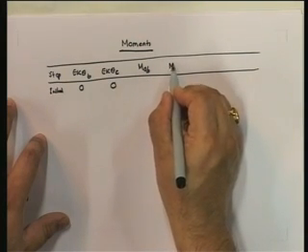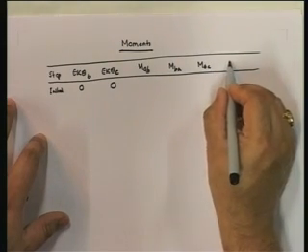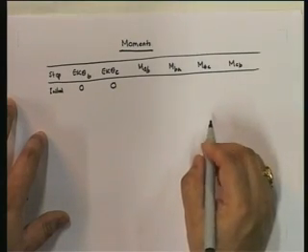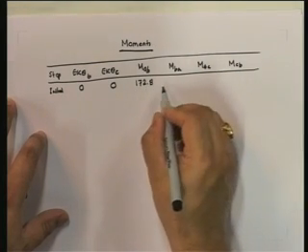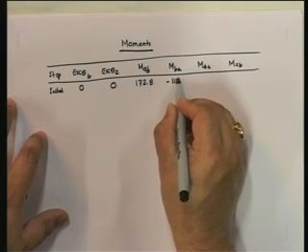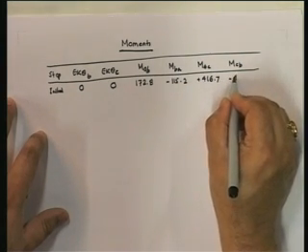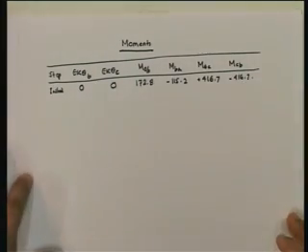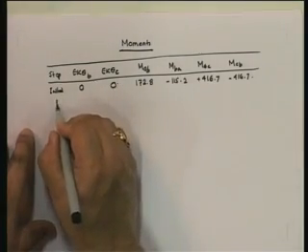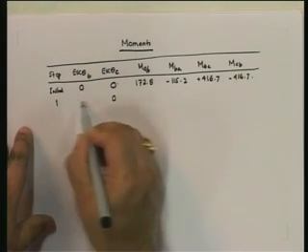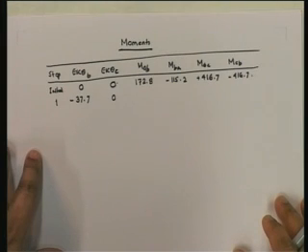Let's see what happens to MAB, MBA, MBC and MCB. MAB when it's 0, 0 is going to land up being 172.8. This is going to be minus 115.2. This is going to be plus 416.7, and this is going to be minus 416.7. So these are the moments when I take theta as 0. Then we have the first step. The first step, what did we say? That we took this equal to 0, and so therefore this became minus 37.7.